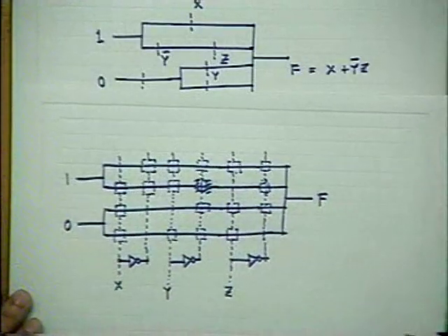Only, in certain locations we put the transistor, and in certain other locations we do not put the transistors. Exactly this we do when you develop a ROM, which we shall be discussing afterward: programmable ROM, mass programmable ROM. There are certain ROMs which are manufactured. If you give your program, or rather your memory requirement, to the manufacturer, they will make it for you, but it will be a permanent ROM. You cannot change it. This is normally done for applications where some millions or at least thousands of such chips will be required. Whereas, as you know, today there are variations, field programmable, etc., coming. I shall discuss that afterward. So that is what is known as structured logic.